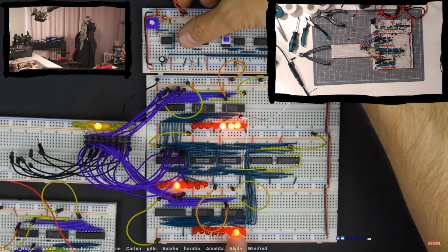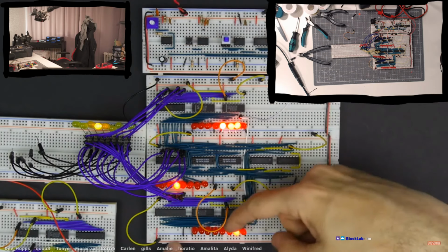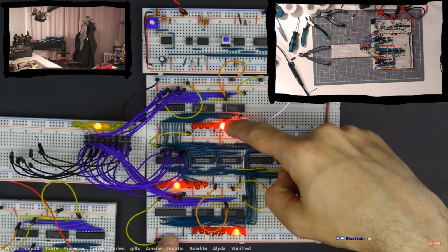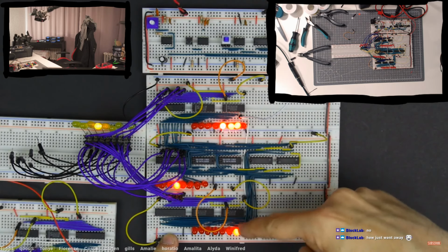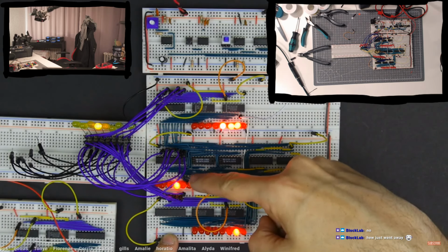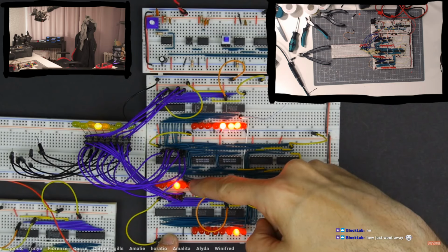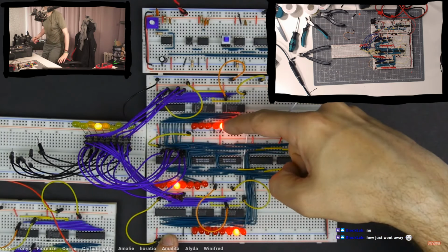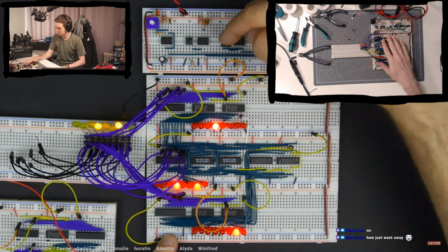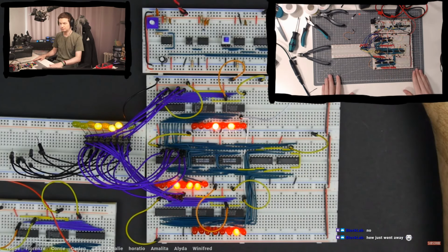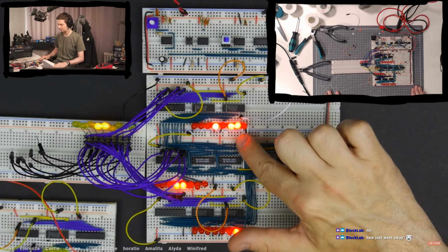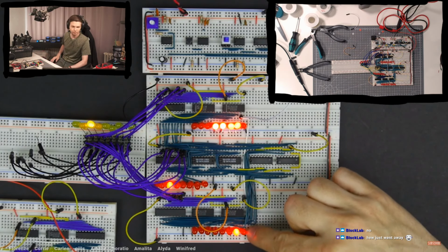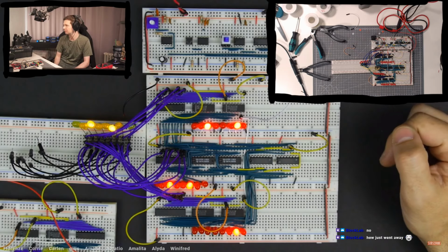And that makes sense, because we have a 2 down here in the B register. And so every time we put a new value into the A register, we're adding 2 to it and putting that into the ALU. And then that's being output on the bus. And so then the next clock, we bring that into the A register. So if we just let the clock run, you see at every clock's pulse, the A register increments by 2, or we add 2 to it, because we have a 2 down here in the B register. And so you can see it's just counting.